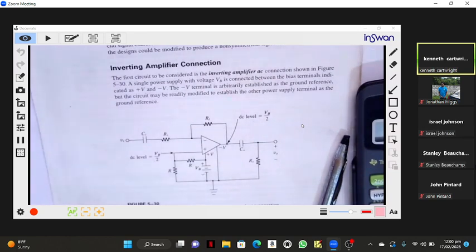Now, when we use op-amps, we have a positive supply and a negative supply most of the time. But creating positive and negative supplies causes problems, and doubles the price of a power supply. So sometimes we operate an op-amp with a single voltage supply.